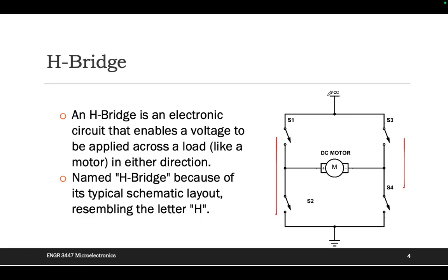And then you can see this is VCC, which means it's power, am I right? This is ground, which means if you connect this one and this one, then your current should be like this. That makes sense to you? And then your motor should run in this direction. If you disconnect those two and connect this one and this one, your current should be like this, and then your direction should be opposite. That's the reason why the H-bridge can control the direction. That makes sense to you?